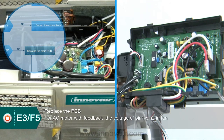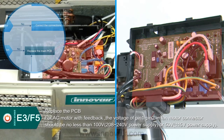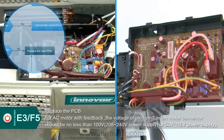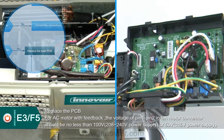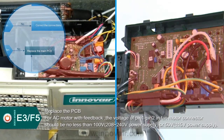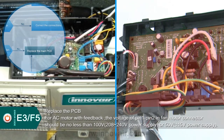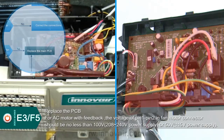Examination for main PCB board. AC motor with feedback. Turn the power on and set the unit as running in high-speed mode. 15 seconds later, measure the voltage of pin 1 to pin 2 in the fan motor connector. If the value of the voltage is lower than 100 volts, 208 to 240 volts power supply, or 50 volts, 115 volts power supply, the PCB must have problems and needs to be replaced.